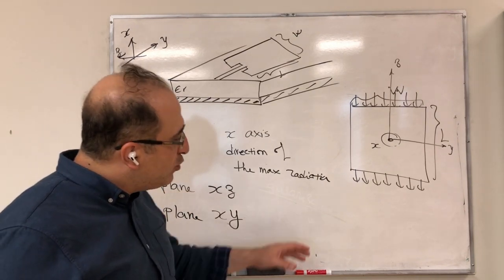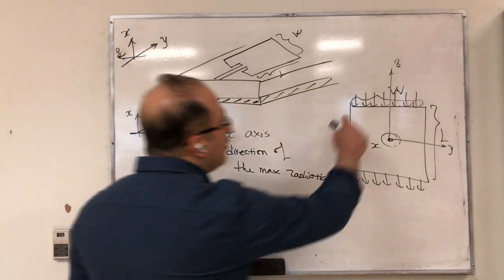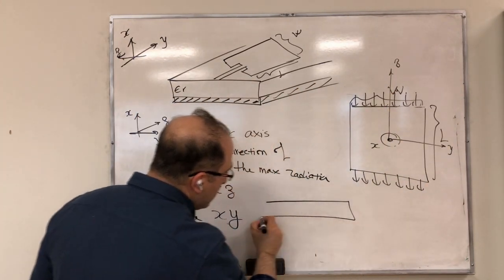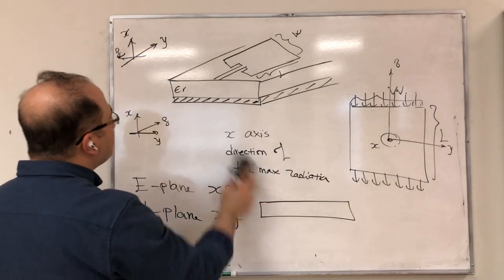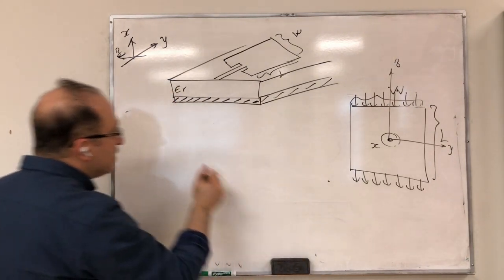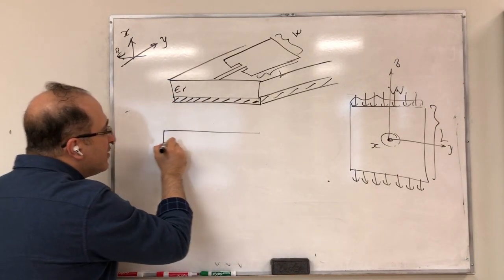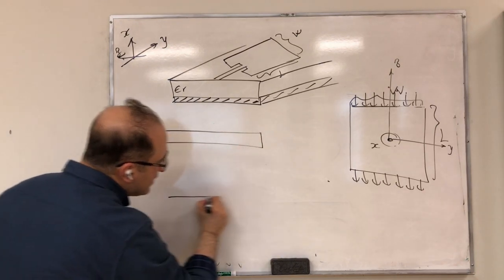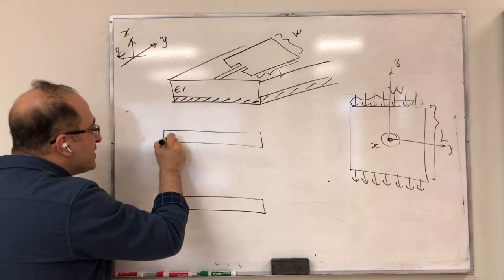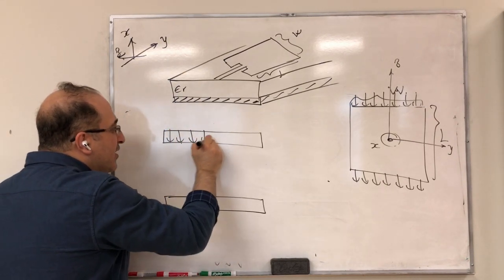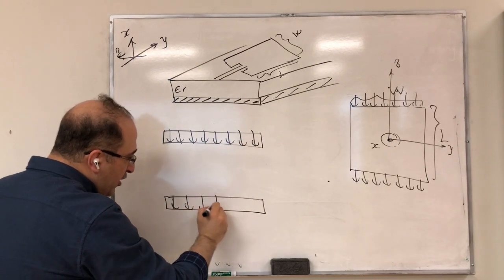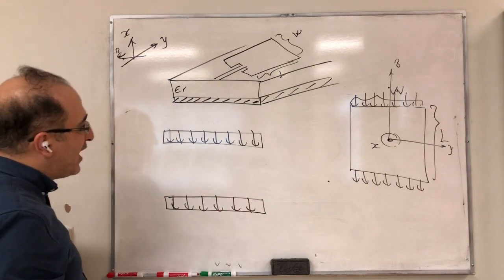So something that you could immediately see here is that if you look at this radiating slot, you have it in this shape almost. So this antenna, let me talk about this antenna within this framework. You essentially have two radiating slots separated by about half a wavelength. And on these radiating slots, you have an electric field, which in the way that I'm plotting is a uniform electric field. So you have that essentially.